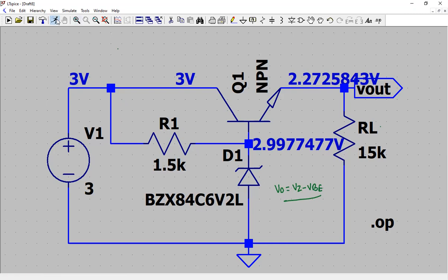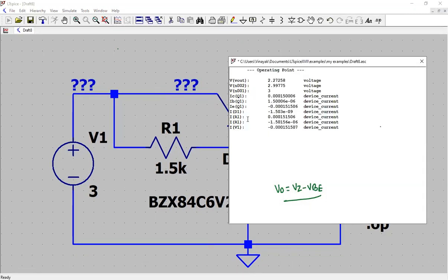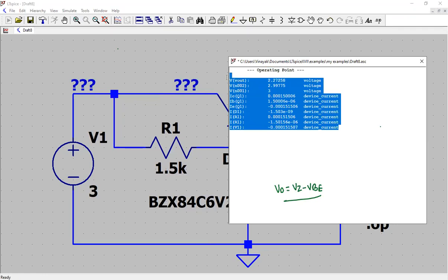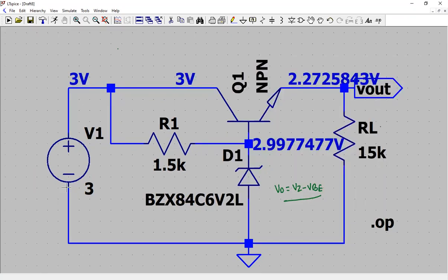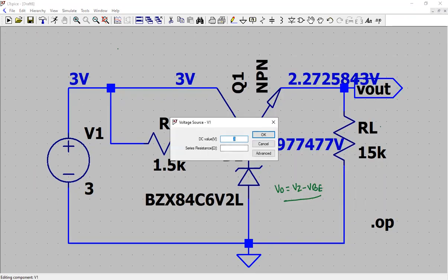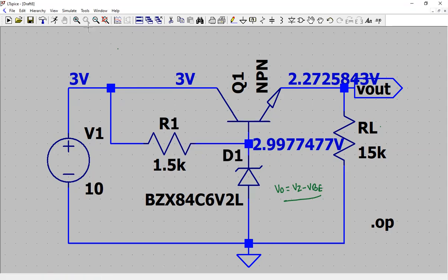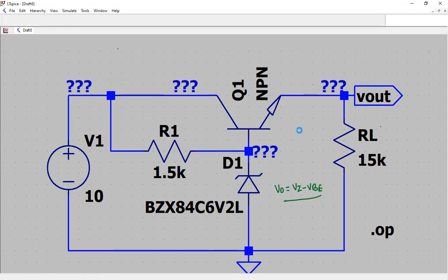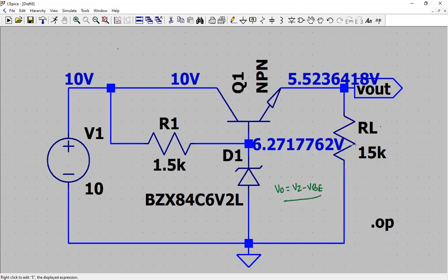And similarly, all these values of the currents and the voltages, you can monitor whether the transistor is conducting and which mode it is and all those things. So all these analyses can be done. So remember, this is how the circuit works, and you can actually do the analysis. There is some other analysis, like you can sweep the values of load or values of the voltage source and plot the output voltage against these variations. We'll see that in a next module perhaps.